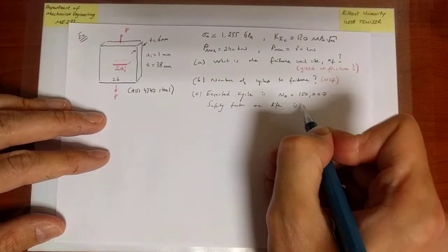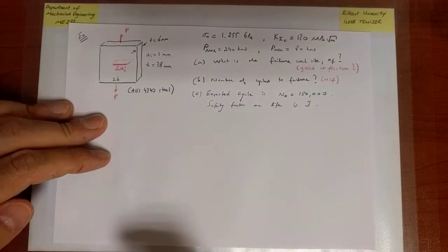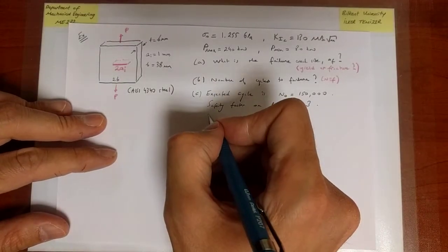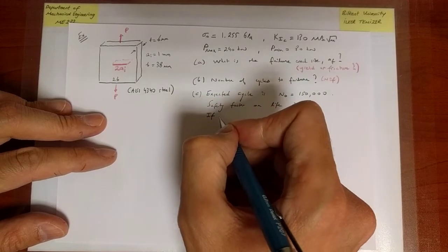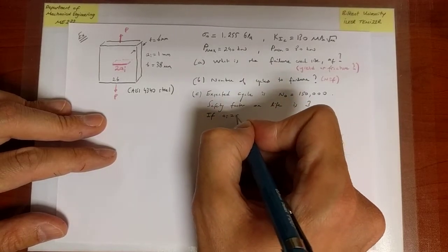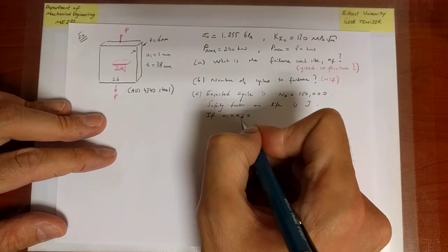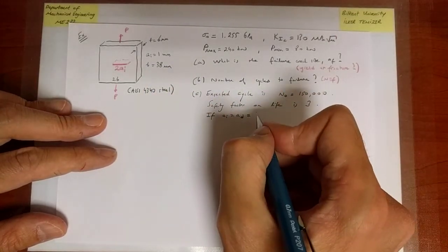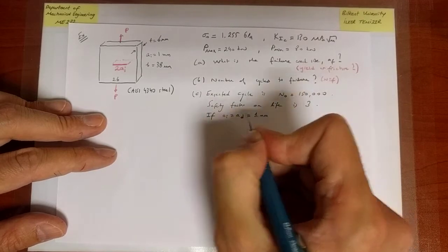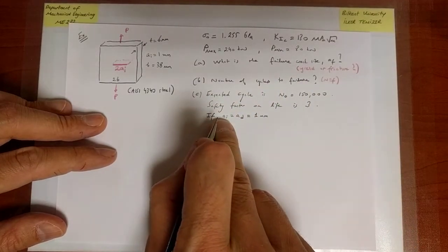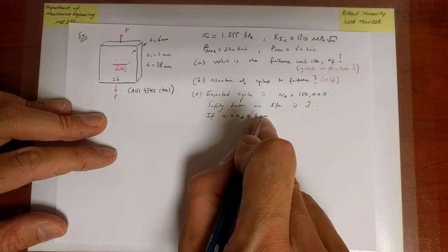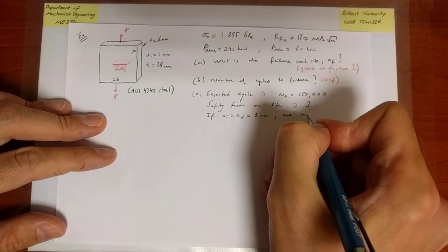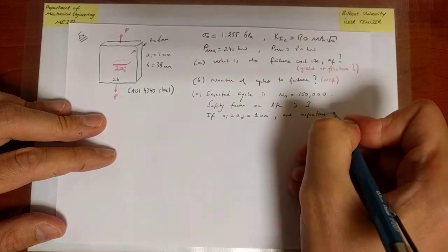Remember, it does matter what it is on. So here it's on life. The safety factor is 3. Okay, so again, let me write down what I've already said. The initial crack size a_i is simultaneously the detectable crack size. So it's 1 millimeter. Although there is no crack, I need to assume that there is an initial crack size of that size. So if that's the case, are inspections needed?